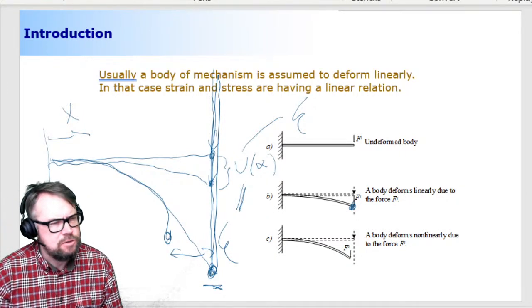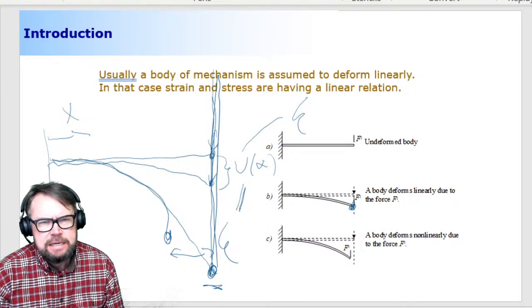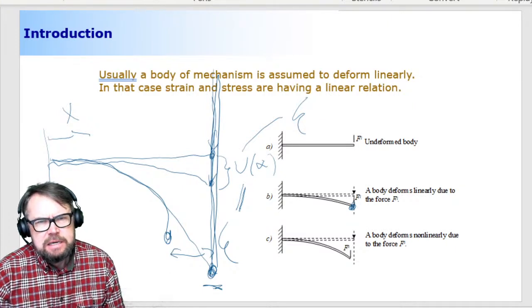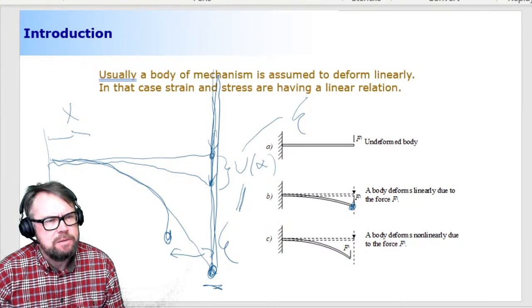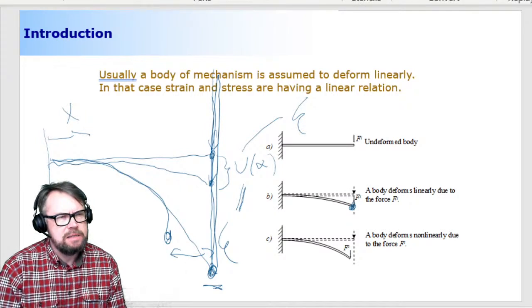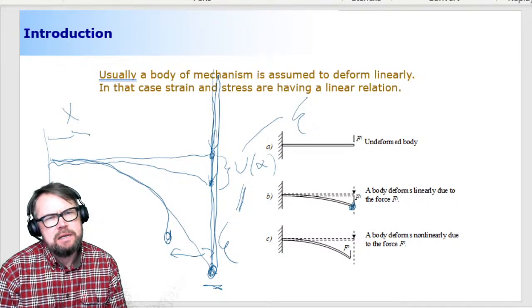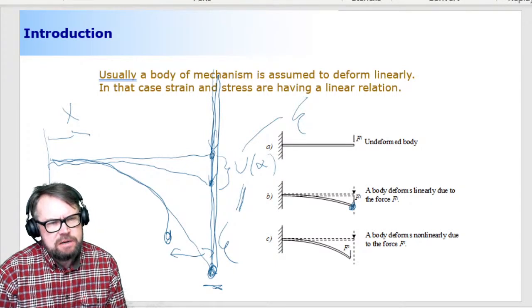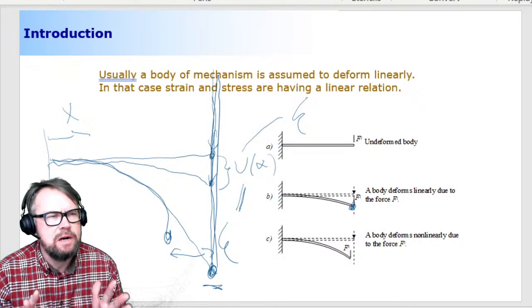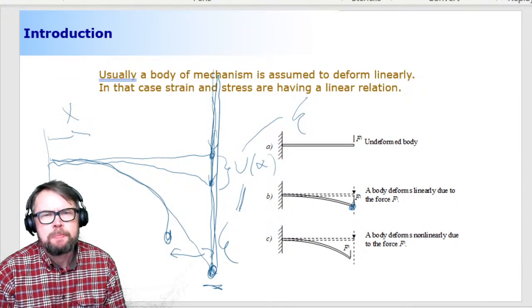In finite element literature and many other literature, this is called geometrical nonlinearity, meaning that the strain-displacement relationship is assumed to be nonlinear. Here we assume it to be linear. In the floating frame of reference formulation, the relation is always linear. This comes with several advantages, such as the fact that you can use model reduction when you assume this relation to be linear.